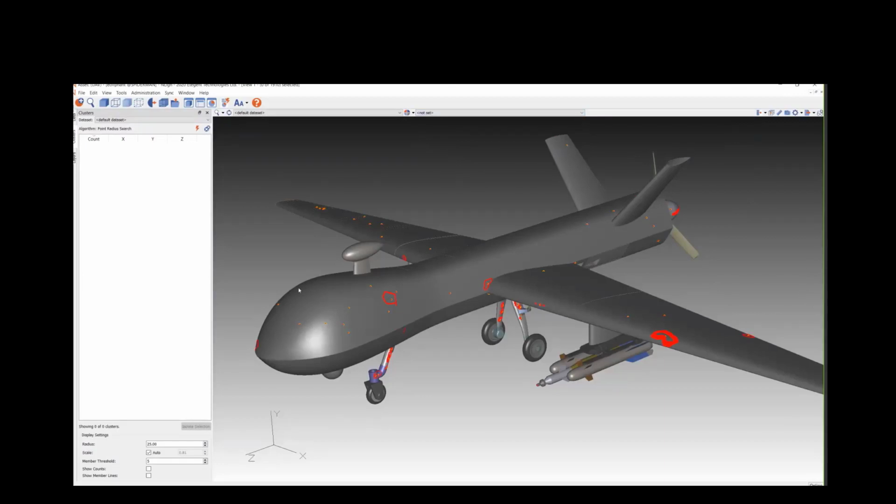Some of these records don't have an outline of the damage, and that might be because they were some type of record that didn't involve an area. Maybe it was a very small dent. Maybe it was some type of part number status, such as flight hours or something like that. So not all records are going to have this outline of the damage of corrosion or crack, but many of them could, as you can see here.